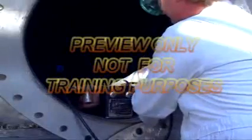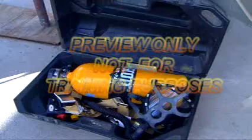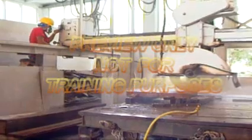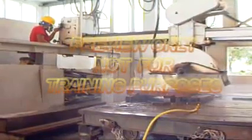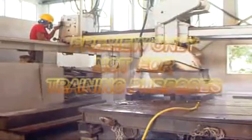Many factors must be taken into consideration when selecting respirators. Workplace factors are very important to consider when it comes to respirator selection. Constrained or tight areas may not permit the use of a self-contained breathing apparatus, even though it might be an acceptable choice. Likewise, working around obstructions or moving machinery that can snag hoses may limit the use of airline respirators.